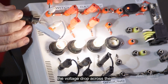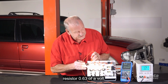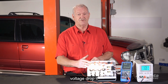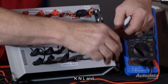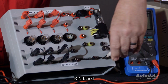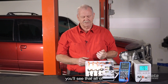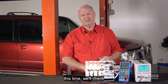If we measure the voltage drop across the resistor, 0.63 of a volt, there's our missing voltage. So a resistance in a circuit will cause a voltage drop. If I move the resistance to replace the wire at K and L, and then turn the circuit on, you'll see that all of the globes are a little bit duller this time. We'll check the voltage drops.